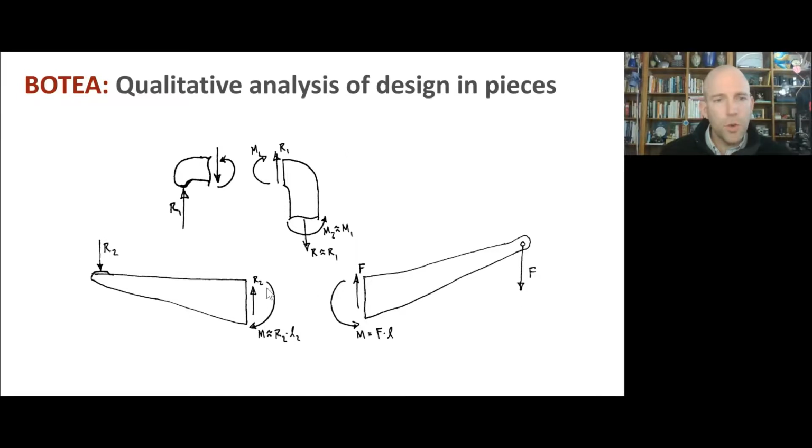And then we have these two arms that stick out. Each of these is more of a cantilever situation. So we have a point load here, and then an equal and opposite force up here, with an internal bending moment at the surface that's internal to the component as a whole. And because we have this bending moment here, again, we're going to want things to be tall. Over here, there's no bending moment or almost none, and that tends to result in lower stresses.